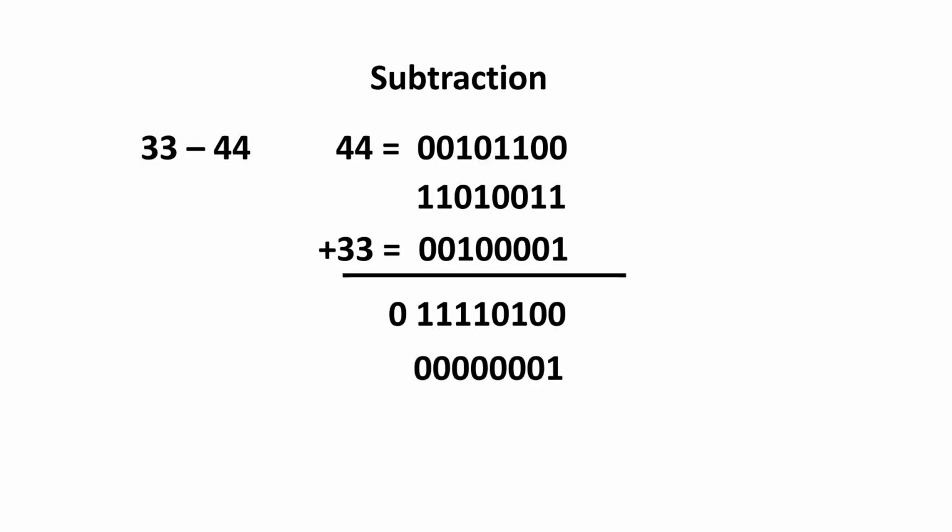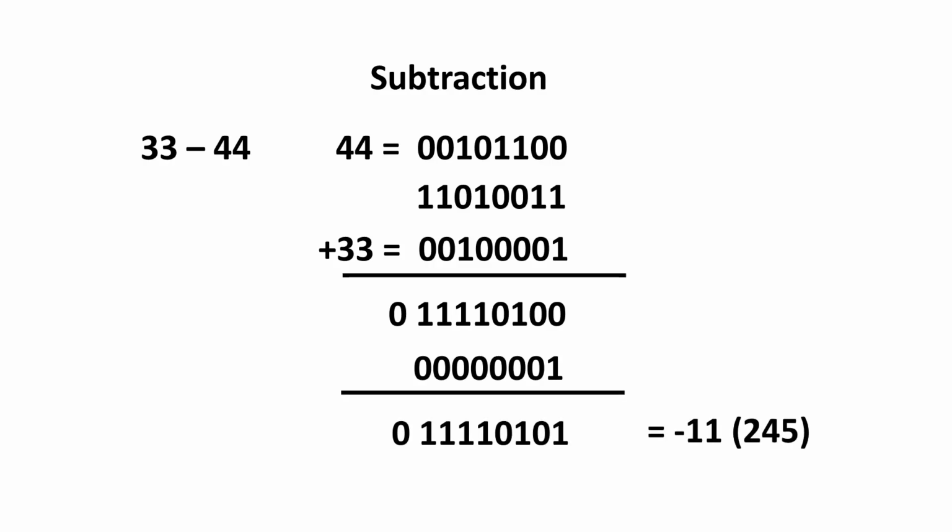There's the 1 from the C register added on. It gives us a grand total of minus 11, or 245, depending on how you view it. So we know that's a negative 11 because the carry flag is a 0. So again, if you were doing the sub with borrow, this is the whole value you'd use in your next instruction.